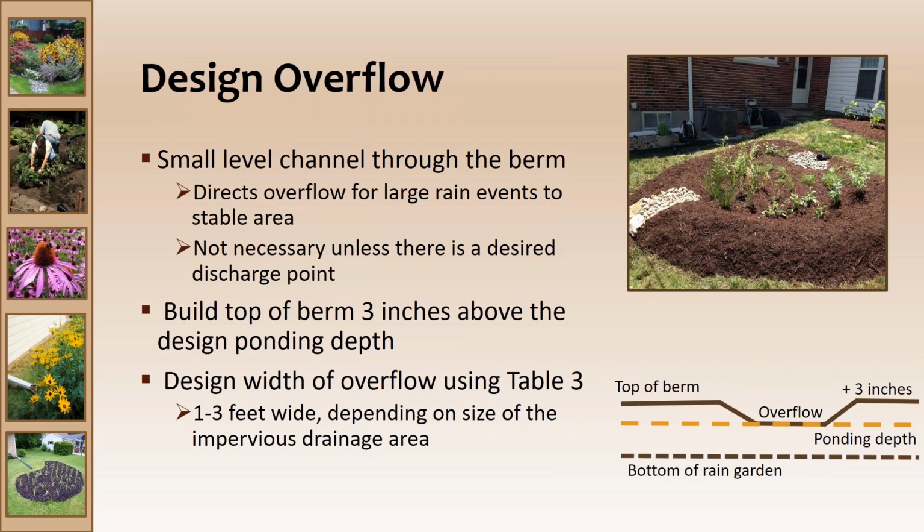The design width of the overflow is actually something that came up, and we ended up creating a table in the standard that dictates what width to use for that overflow, which is a 1 to 3 foot range depending on the size of the impervious surface drainage area above it. So it's pretty easy to use.